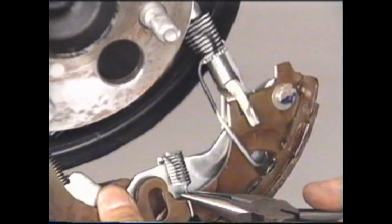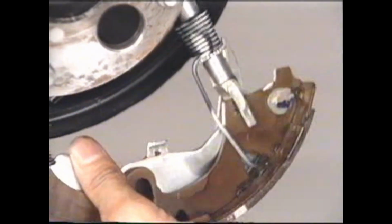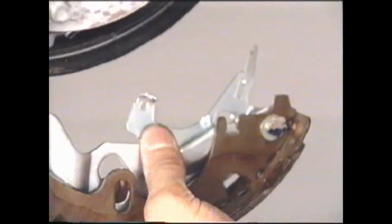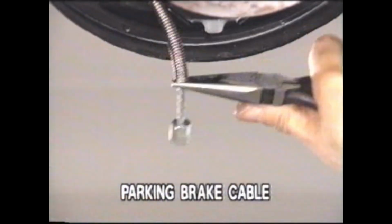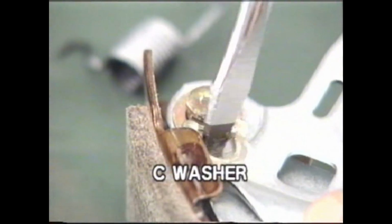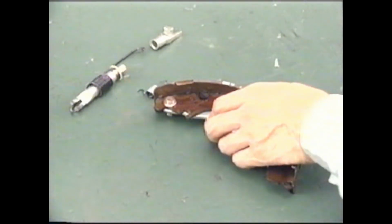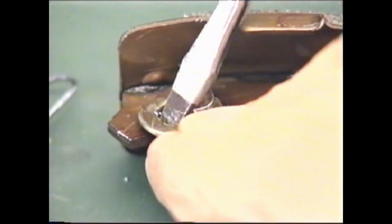The parking brake cable has been removed from the anchor plate. Remove the parking brake cable from the lever using a pair of needle nose pliers and remove the rear shoe along with the strut. Remove the automatic adjustment lever by pulling up the C washer with a screwdriver. Then remove the parking brake lever from the rear brake shoe by pulling up the C washer.